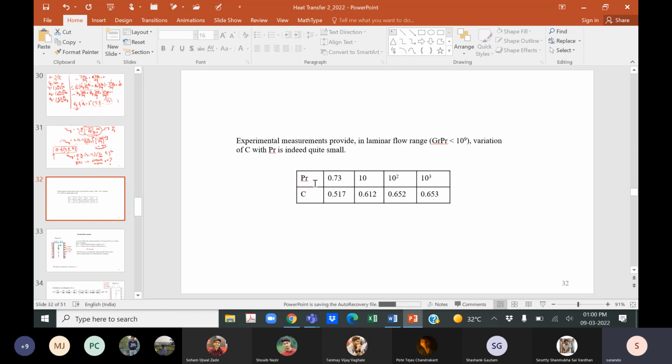But we all know the application of liquid metals, as they have very high thermal conductivity. So they are perfect material for extracting heat from nuclear reactors. And with our analysis, we won't be able to apply this sort of a relation for the case of liquid metals. So apart from liquid metals, for any other fluid, we should be able to use the concept that is developed in this course. And I will tell you in Friday's class how to handle liquid metals.